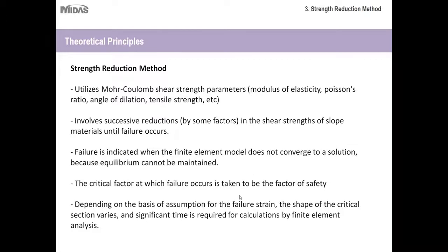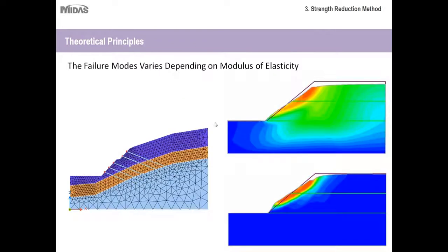But once again, as engineers using modern programs, the main thing is to understand what you're inputting into the program, so these will be your strength parameters, and then also understanding how the analysis is done, and interpreting the results. We'll be going over each of those in this section. Even though we won't be directly discussing the exact equations or, in detail, the theoretical concepts used for the strength reduction method, we'll be gaining an understanding of the process that's taken.